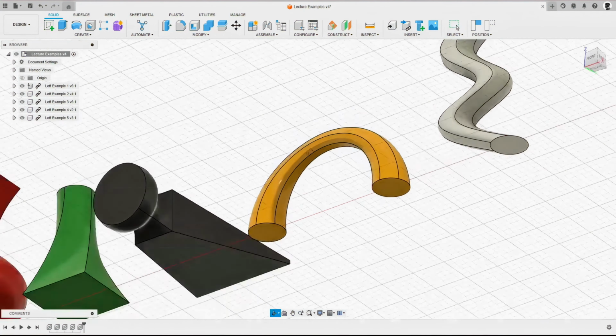So this one here, we start to see that preview form already. Now let's see how that preview changes when we select this profile here. Okay, we get that nice arc, nice curve coming in here. And then last but not least, we'll select this profile here. Everything in the preview is looking good. So we're just doing profile modeling here. So we're only concerned about this box. We're not concerned for the time being about guide types or rails, but we will cover these in a demonstration after. So we can click OK there.